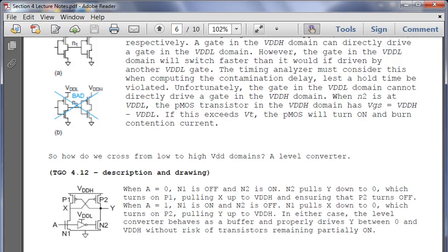And so this is actually an issue when you're trying to do low power design and you're trying to do clock frequency scaling and clock gating. You're going to have a little bit of trade-off in area to be able to ensure that you can properly power each portion of the circuit.